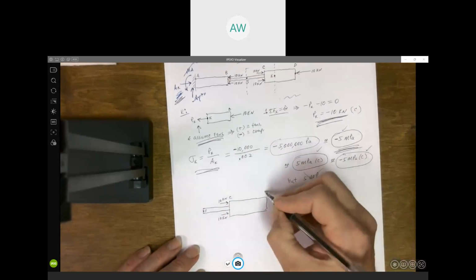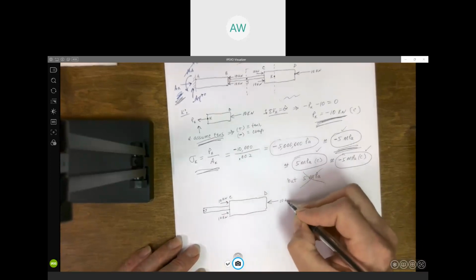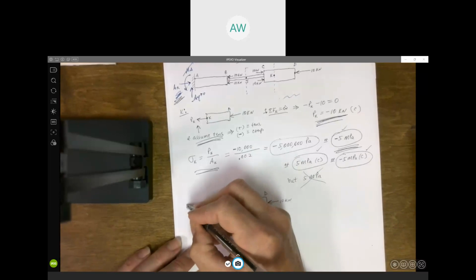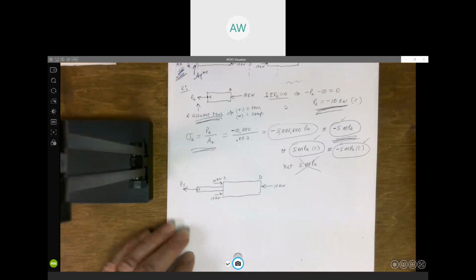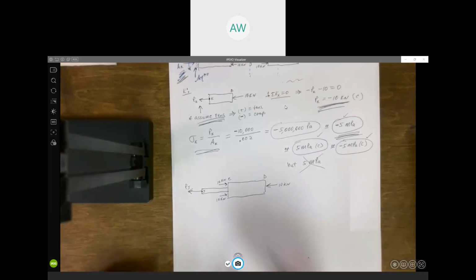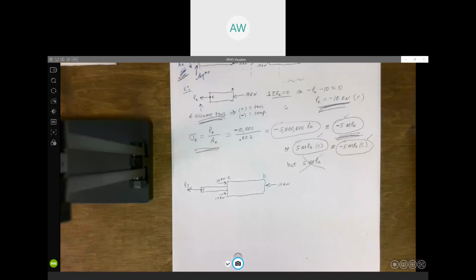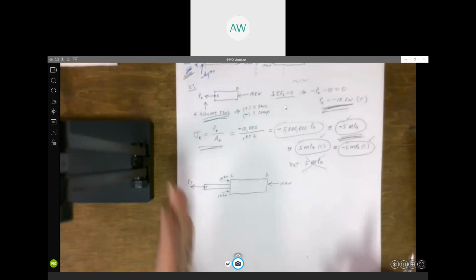Again, this is C, this is D. We got 10 kilonewtons here going to the left. And we want to find what this is. This is J. What is the axial force acting there at J? Again, I'm assuming tension, so that way my plus or minus will correspond to tension and compression. But notice I've drawn everything to the right of where we cut it.